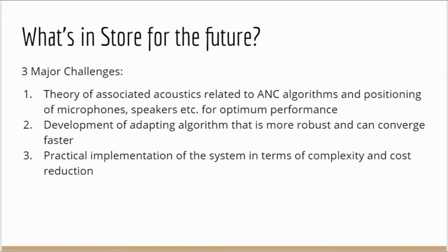For further studies, there are still three major areas that are in need of development. First is theory of associated acoustics related to ANC algorithms and positioning of microphones, speakers, etc. for optimum performance. Second will be development of adapting algorithms which are more robust and can converge faster to the incoming sound signal.